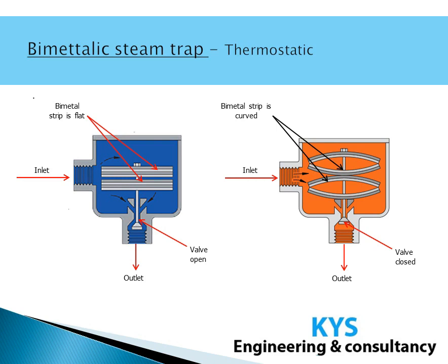The operation of a steam trap takes place at a certain fixed temperature, that is predefined temperature when it will be closed, at what temperature it will be closed. Due to heat loss to surrounding by trap body, temperature decreases inside the trap body and the valve reopens and starts discharging condensate, and thus cycle gets repeated.